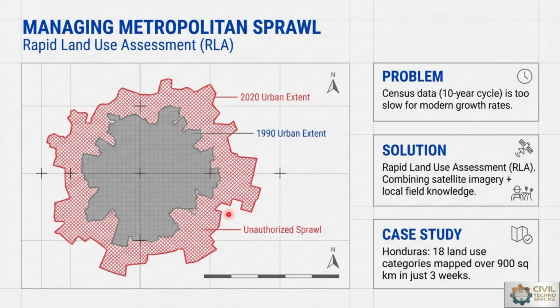Here we see that remote sensing is more useful from the planning point of view. That planning is for population density, highway alignment, railway planning, traffic corridor analysis, or any network analysis. Satellite images help to identify the existing city population and infrastructural land use land cover, and the forecasted land use land cover, with reference to roads, terrain, water bodies, settlements, and environmentally sensitive areas also. Here the digital elevation model plays an important role in slope analysis, selection of economical transportation routes, and many more assessment tools also.